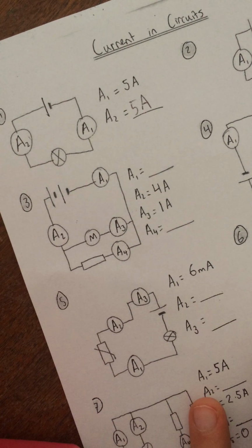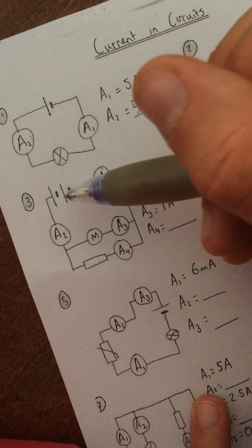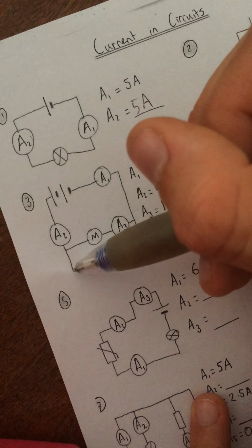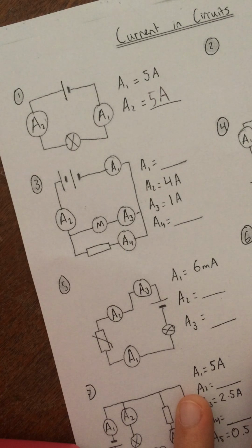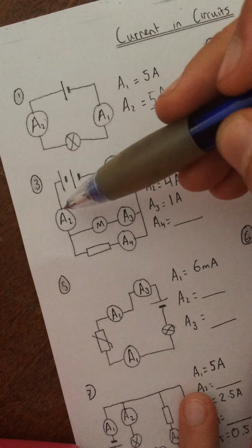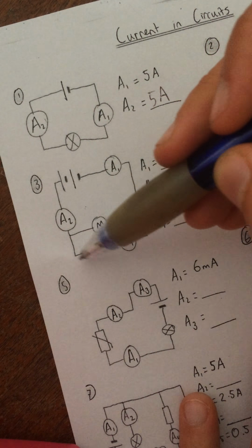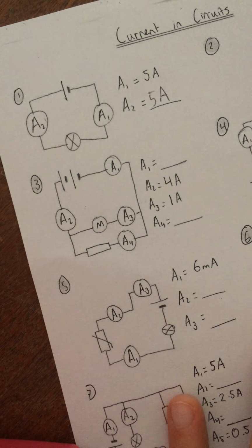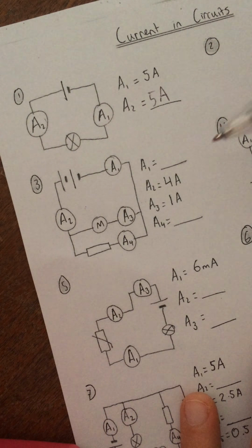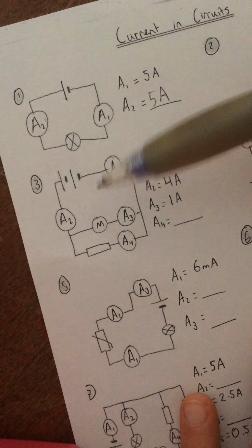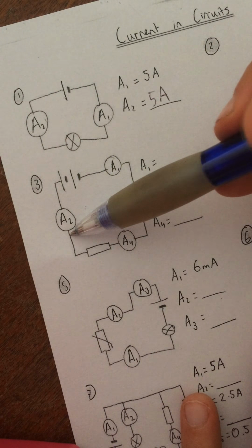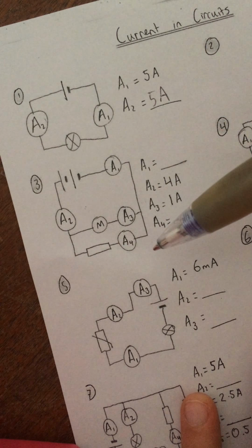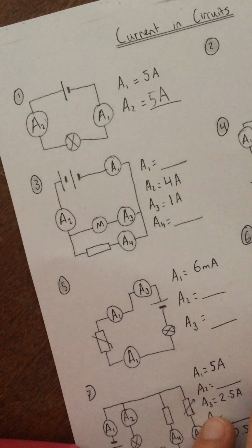Question 3, parallel circuit because the wire splits, goes in two directions. The rule for current in a parallel circuit is that the current splits. So the current that we had before a junction must be the same as the current we have after the junction. So first off, if at ammeter 2 over here we had 4 amps going into the junction, those 4 amps split in two directions. That does not have to be an equal split.